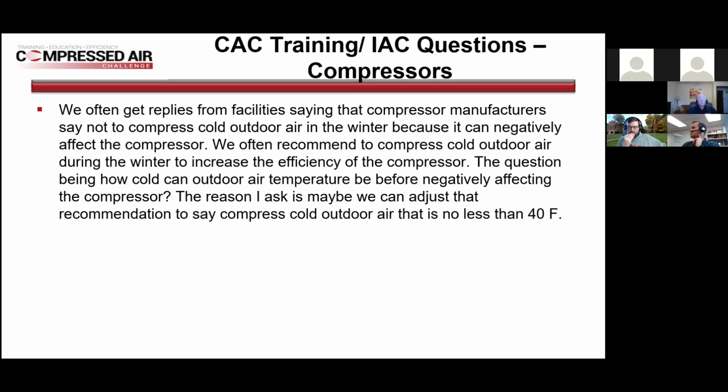And if you don't have heaters to get it going, you could cause issues and problems there. It may cause a little bit of condensation in there too. There's a couple ways you could get around it. You could put in indoor actual dampers to close off when a compressor's off. That's the one I've heard the most, and it really is around the maintenance and the oil conditions. The rest of the ones, for the oil-free, they still have a little bit with the lubricant that's there, but that one's more on the temperature of the cooling water and it recirculating all the time. So that's the biggest one that I know of.